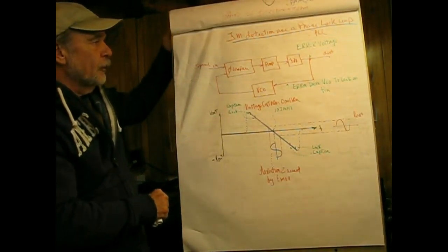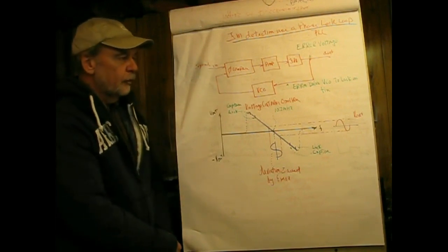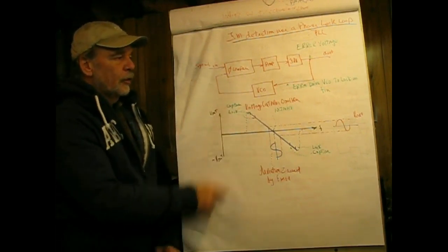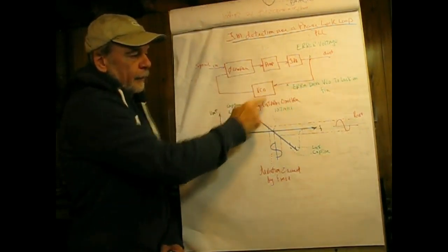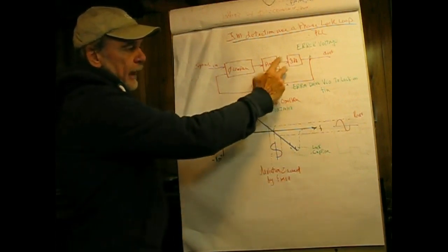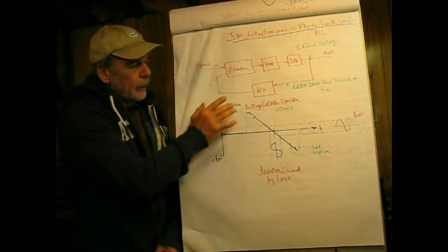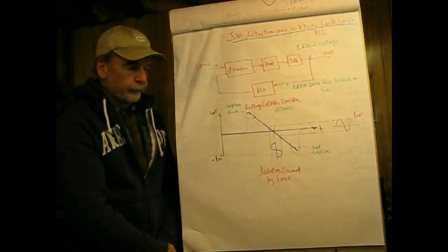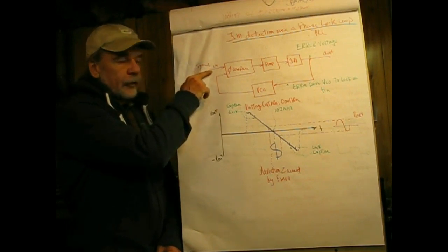So we can also detect frequency modulation by using a phase lock loop. That's a PLL, is abbreviated. And inside of a phase lock loop there are 4 blocks. Well, one is a phase comparator, the other is an amplifier, another is a filter, and it feeds back into a voltage controlled oscillator. Now, as I've drawn it, the amp and the filter may be reversed, but the spirit's the same. So what happens is we set the VCO to a free-running frequency, which, say for detecting FM, would be 10.7 megahertz. Then we apply the signal here.